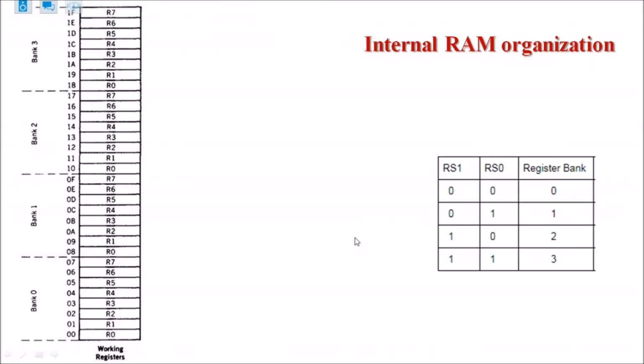The size of internal RAM is 128 bytes. So the addresses that we have also seen, the address of RAM. The memory is growing in upward direction in 8051. For other controllers, it may grow in downward direction, but here it is growing in upward direction.